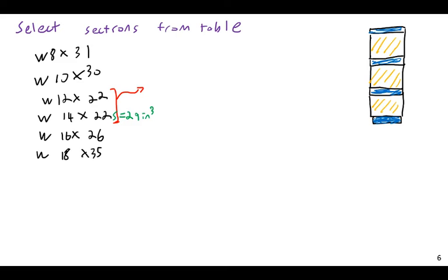Whether you have a 6-inch deep beam or a 24-inch deep beam, they don't care. It's only a single-story building. So depth isn't important in this example. We'll keep things simple, so let's just select a W14 by 22. We get more strength for the same cost.